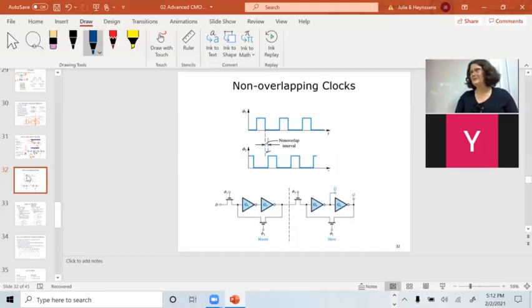And you can tune these things. Oh, this is what Bruce would do. He'd sit there and tune these overlapping edges of the clocks. You'd actually have to delay the other clock and invert it, and make circuits that would act as delay lines for the clock by tuning the size of the transistors and everything, and get them so that your setup and hold time was basically equal.